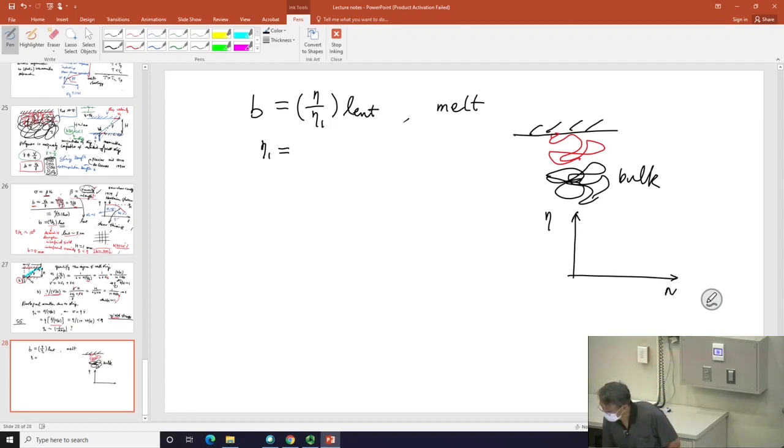Just a piece of knowledge that we may not have discussed many times. I mentioned before in discussion of repetition that the viscosity of a polymer is heavily molecular weight dependent when you are exceeding a certain critical molecular weight. Before that, the relationship between them is linear. I'm drawing a double log plot, so the slope is the exponent. So this is indicating that viscosity here goes with molecular weight to the 3.4 power.